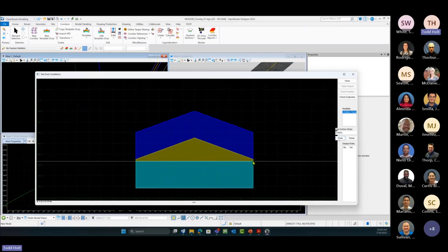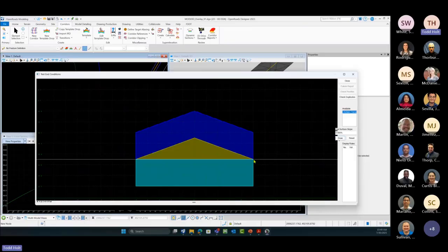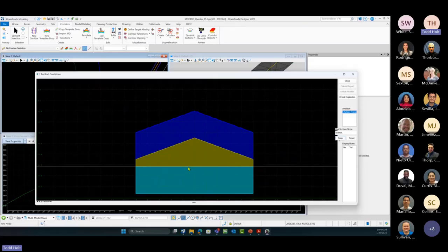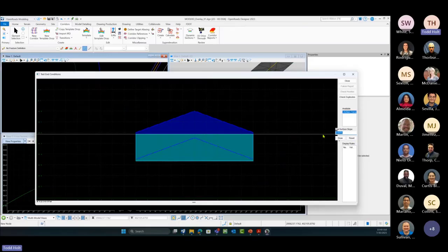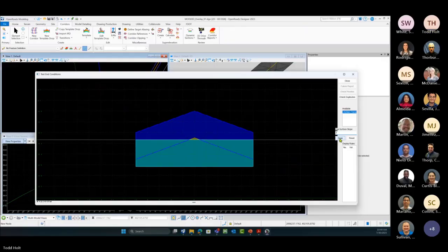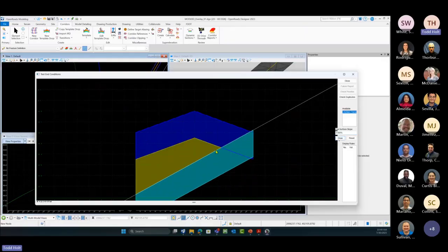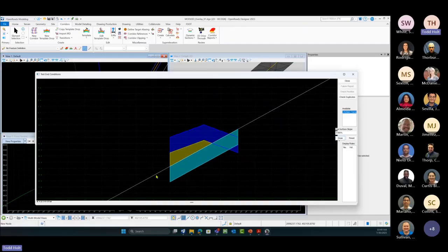I didn't really show this, or this is a good test too. It's going to mill down the 3 inches or the 4 inches, whatever we define in there. This was 3 inches from that existing ground, and then it's going to build back up the overlay to that. And if we check in to draw, say, a 3% and draw that in, so we're milling down 3 inches.